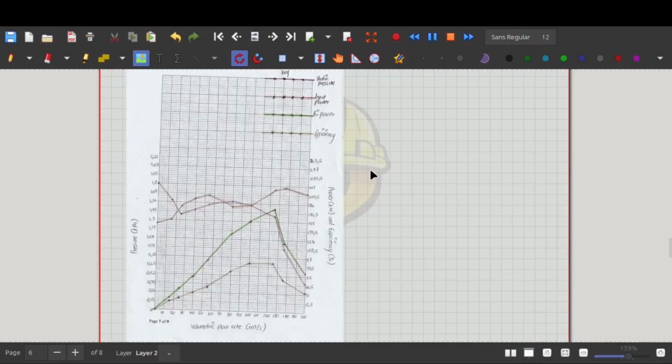Now, a few things to note: this is information from the laboratory. We may need to make some adjustments when we take it underground. You might find that you have a different air density, or a different fan speed when you get to the underground environment, so we need to do adjustments.